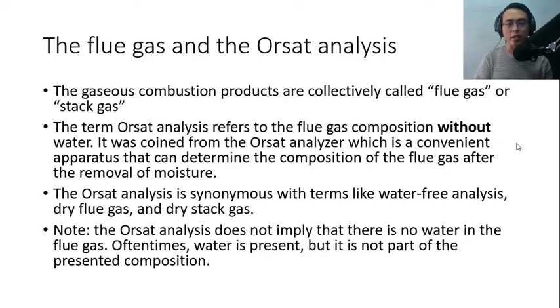The term Orsat analysis refers to the flue gas composition without water. Now, some of you might be asking, isn't water one of the primary products of combustion? Yes, it is. We are still maintaining that there is water in your flue gas, but the Orsat analysis reports the composition excluding the water. There is still water, but we are not including it in the Orsat analysis.